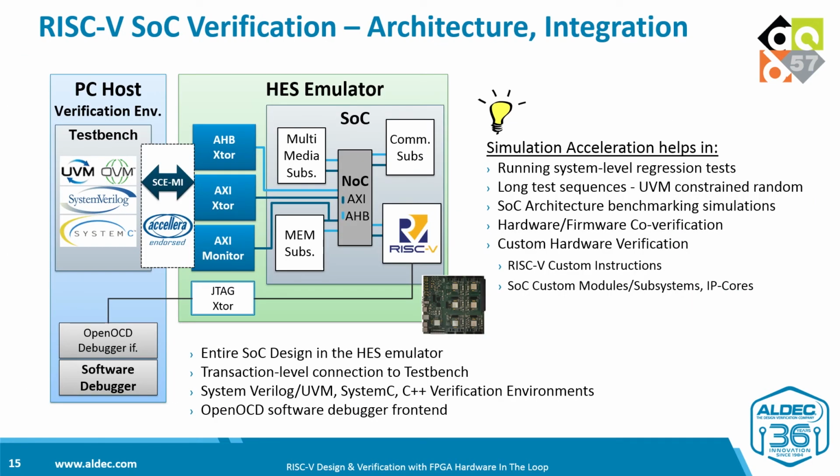Let's take another example of emulation, which is the case of integrating the entire SoC and performing system-level verification. Now, the emulation can be used either by a hardware team or by a software team. The hardware team can use emulation to verify system-level integrity and requirements, as well as run regression tests after each update committed by developers. In this case, the idea of using or reusing the system-level test bench for simulation and emulation is the same as before at RISC-V core level verification.